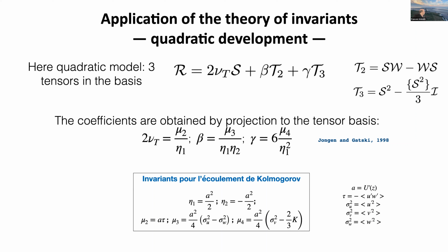Yes. In fact, what was surprising when we compare the two is that with Kolmogorov flow, where we have no wall effects, it seems to work better for larger shears. So it could be seen as an effect of the wall, perhaps. But it was surprising to see that it's almost working in some parts of the Kolmogorov flow. So basically, the region with no shear is maybe not the main problem, let's say.